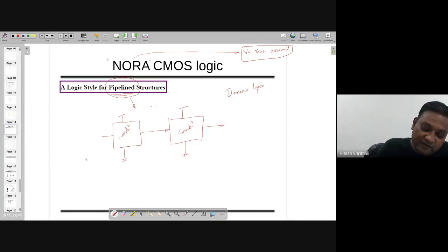where what we have done is we checked whether it's a power up device or a power down device which you are using. If it is power up, you made sure that if this is going from 0 to 1, here also all the inputs have to be 0 to 1, and for that we implemented one inverter in between. This was one thing.